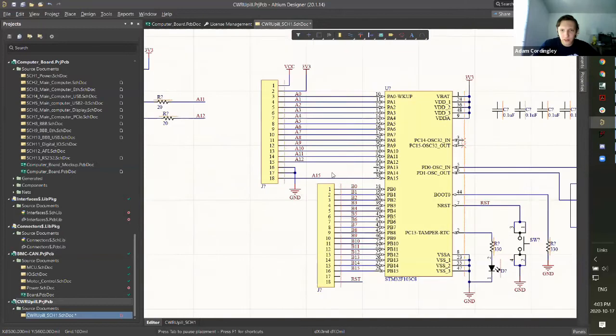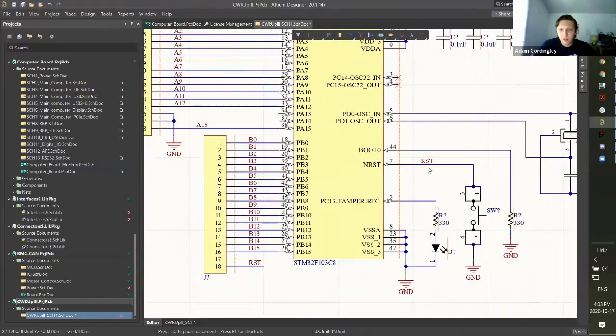The next thing I want to do is take this node here, which is lighting an LED, and also have that on the pin headers over here. The way I would do that, I don't want to draw a wire because that's kind of messy. So I want to name this net with some name. You go up here to this symbol and right click, and you can hit net label, and that's what I want.